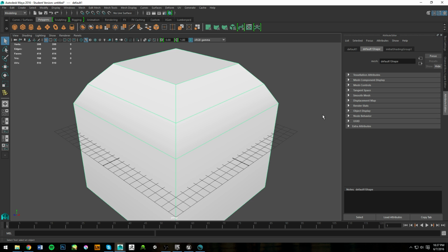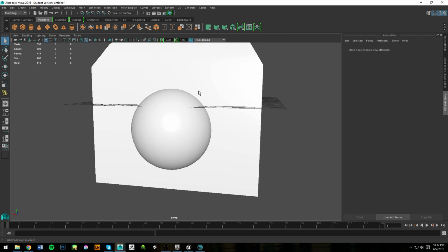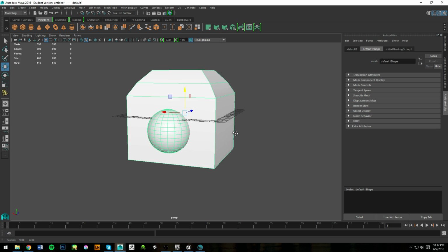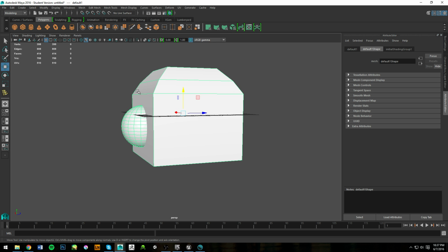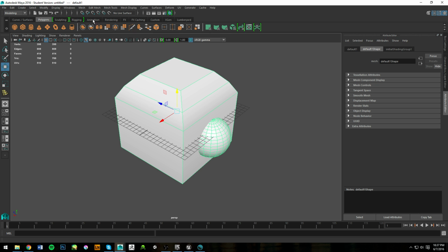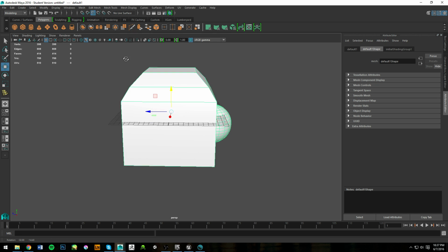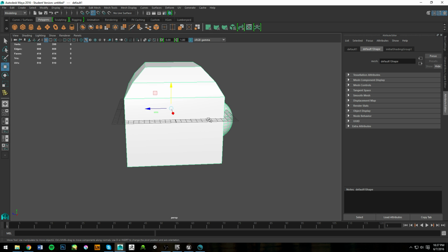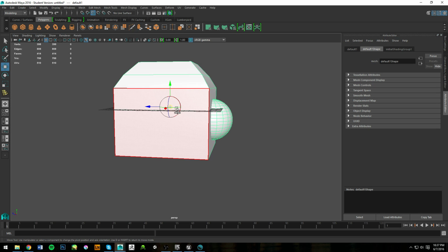And here it is. Now that we're in Maya, we're going to find the pivot point, which we do by just pressing W. You're going to want to turn point snapping on for this. Once you have your object selected, you're going to want to press D. When you press D, it unlocks this pivot point, and we need that very much.